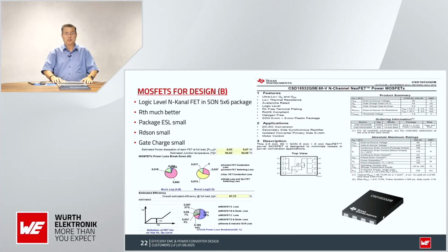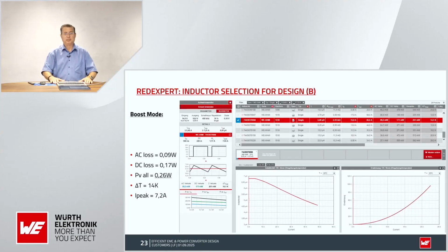Now for the MOSFET, I will change from Infineon to the Texas Instruments one. It has a much better package, an extremely small ESL, RDS(on) is very small, very good thermal resistance. It costs a little bit more, but it will be paid back.